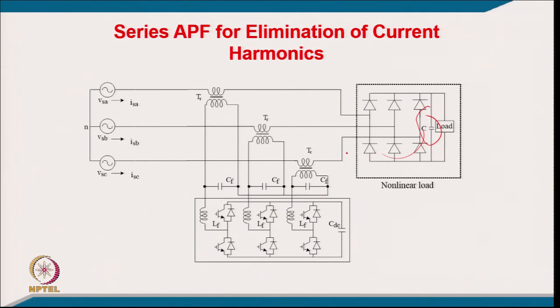The same kind of waveform will appear here, because the same DC link voltage will be reflected here when all 3 phase diodes are conducting, meaning all the time, typically 180 degrees for the positive cycle and 180 degrees for the negative cycle, and only then can the current be in phase with your supply voltage. So, by injecting a suitable voltage, it can eliminate the harmonic currents. You are virtually blocking all the harmonics which were flowing uncontrolled in this non-linear load.